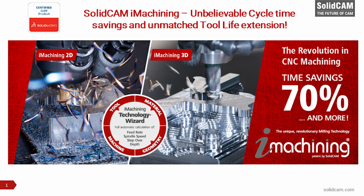Well, if you think about what we talked about with the physics that's going on there, the constant chip thickness means that the latent energy of plastic deformation is going to remain very, very stable, which means the force load against the tool and the machine is not going to be variable.